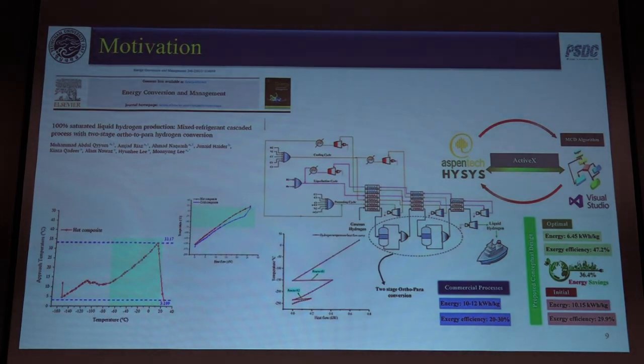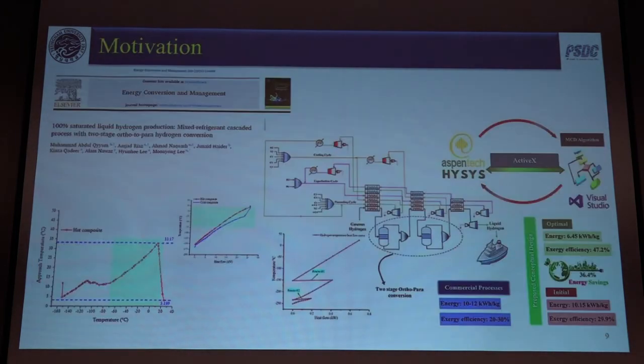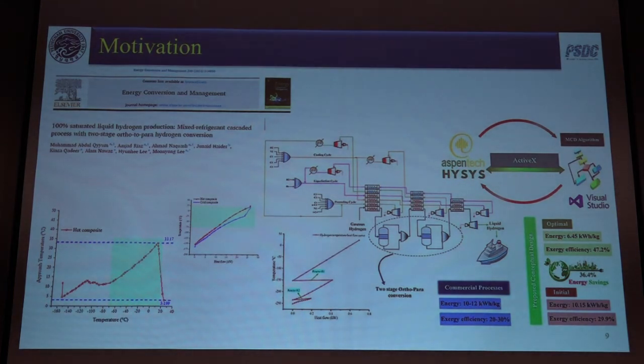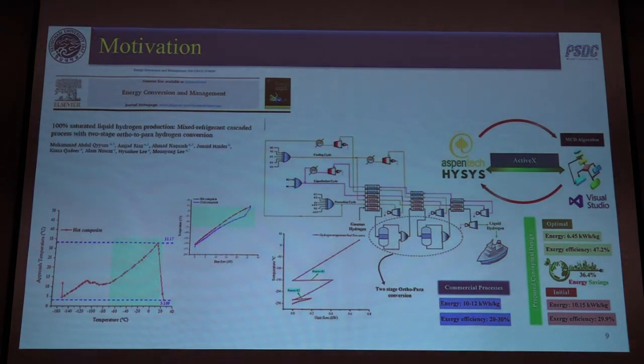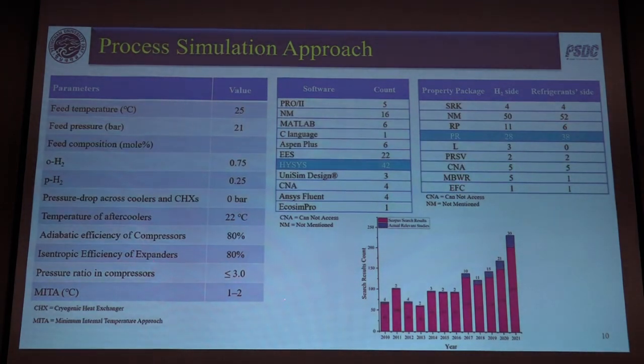For that part, we tried another simulation with the introduction of, since it is at the hot end, we need a high boiling point temperature. That is why we chose hydrofluoroolefin. It has already been studied and used for LNG cases as well. So we tried it here. And before I go into the detail, let me show you the simulation assumptions that we usually take.